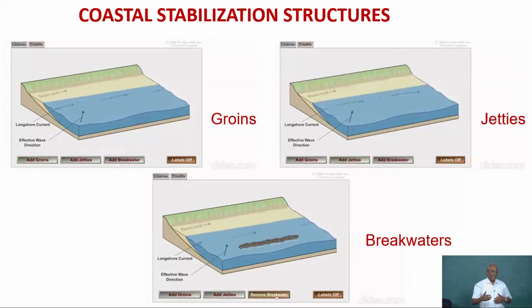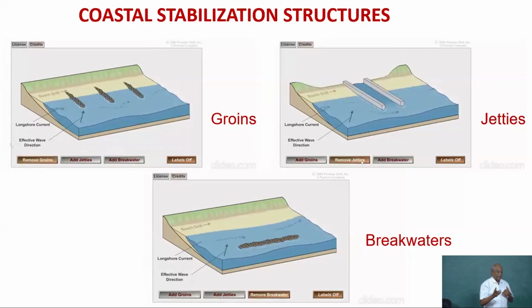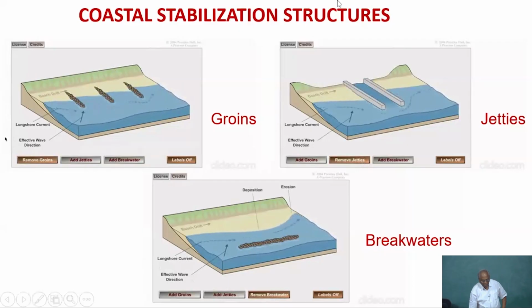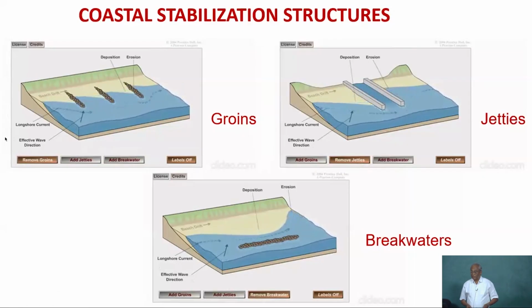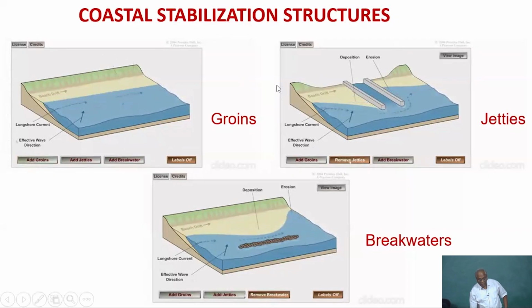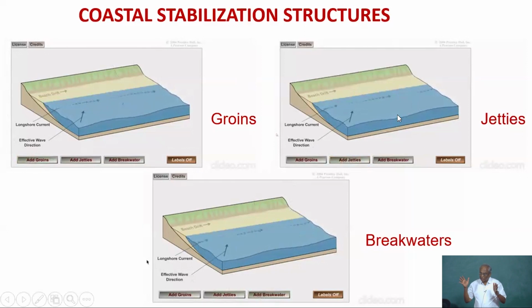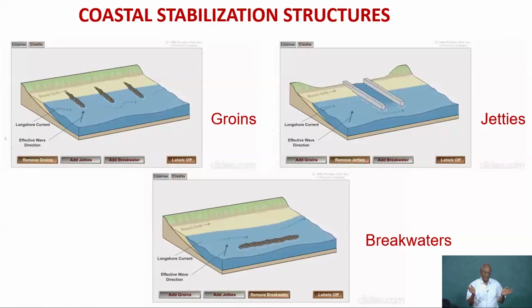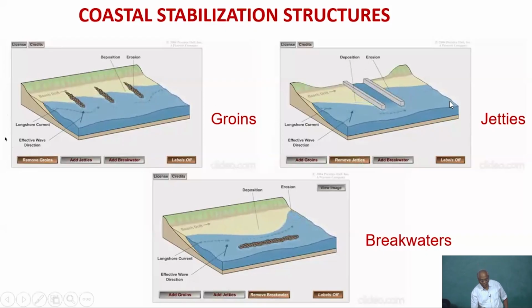But when you trap the sand, you have to be careful, because this sand is moving, as I said, within the surf zone. And this is a problem. For example, if you have a river mouth, and if you don't have any protection measure, then this is going to become closed. You know, when the river mouth is getting closed, then you have other issues, the stagnant pool of water breeding mosquitoes, etc. So you have to have two what are called training walls, as you can see here.